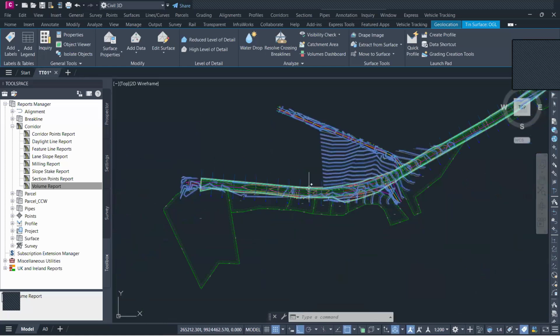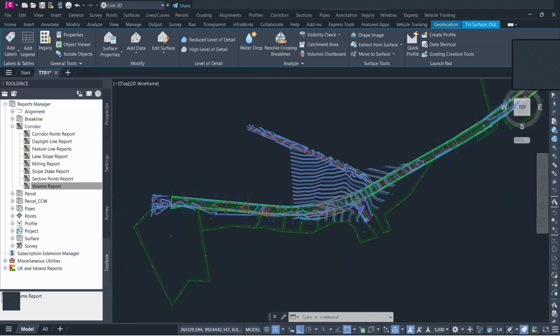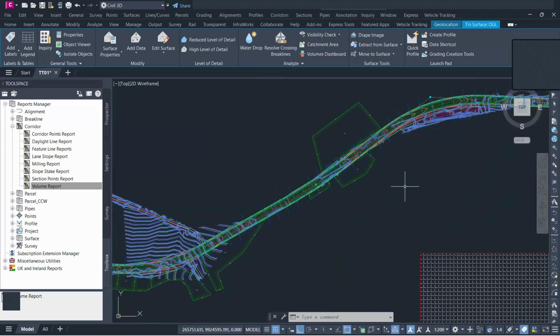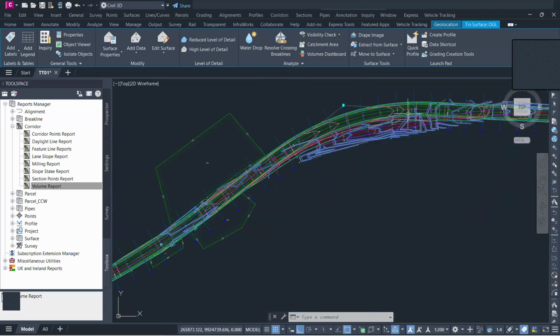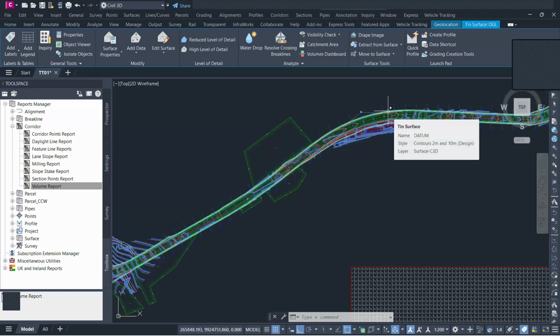That is why, as we said, when the surveyors are doing the engineering survey, if you import it and find sections of the road that are not within the surface, you instruct the surveyors to go back and do adequate surveying. They will go back on site and collect extra data on sections outside the road corridor. Otherwise, if you don't have a surface in that section, you will get the volume quantities wrongly.